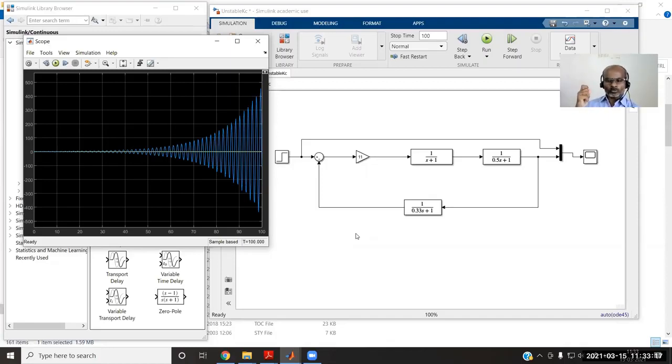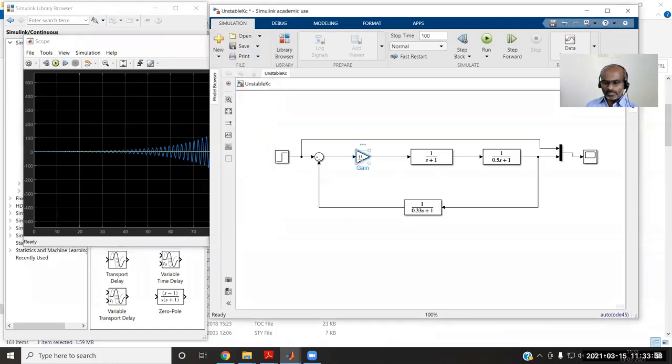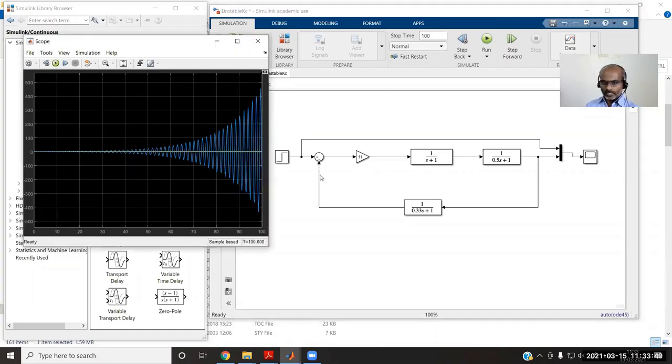With D control, we can slow the response of the system. That is also helpful. We can understand the effect of D control in the coming topics. And if you try to eliminate the offset by the simplest controller action, P control, with keep on increasing the gain, at some conditions you see that the system is turning to an unstable condition.